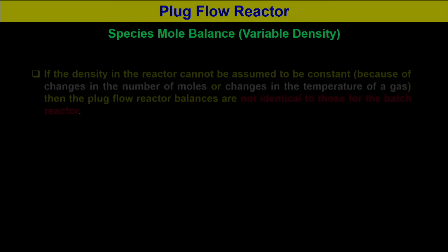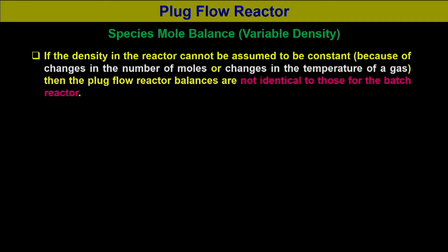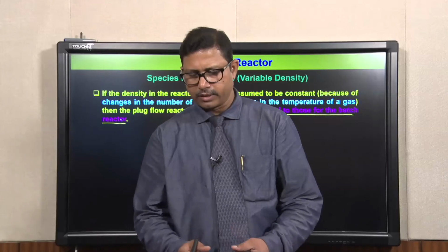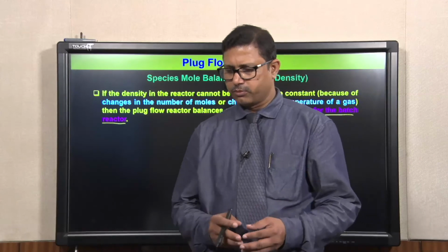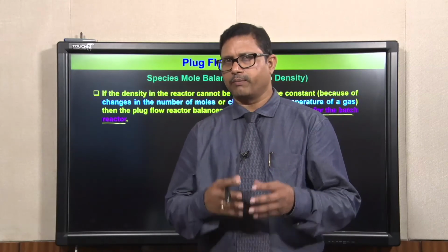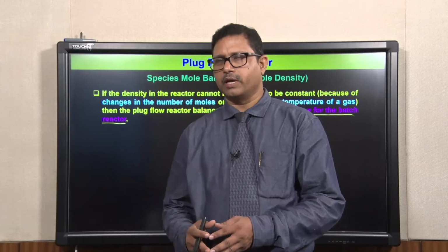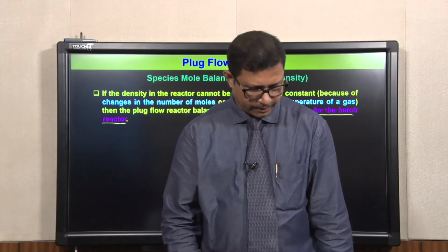Now, if the density in the reactor cannot be assumed to be constant because of the changes in number of moles or in the temperature of the gas, then the plug flow reactor balance is not identical with that of the batch reactor. So, for variable density system, the species mole balance equations between the plug flow reactor and the batch reactor are not identical.